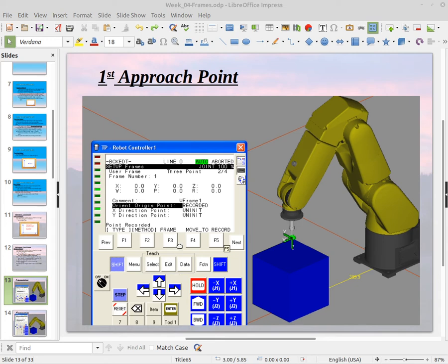Then I will shift it in my X direction, which for this robot, now notice the XYZ that is showing there on the screen at the tool center point at the teach tool, that is based on the tool frame. That is the tool frame's X, Y, and Z because we're clicked on the TCP globe there.